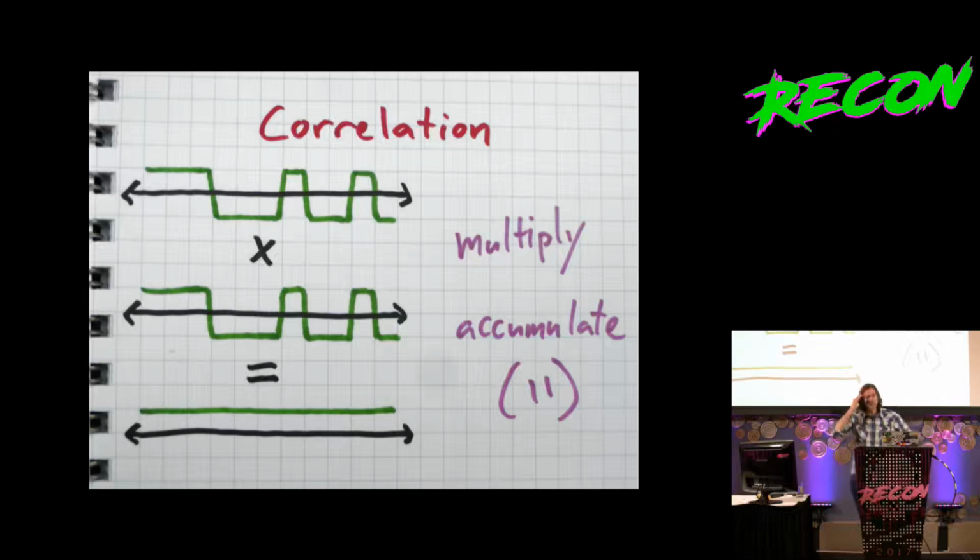So a receiver is able to recover the information that was transmitted by using this correlation algorithm, and the correlation over time will be near 0, near 0, near 0, and then a big spike, maybe 11 or near 11, when a 1 is transmitted, and then near 0, and then a low spike when a 0 is transmitted, and then back and forth.